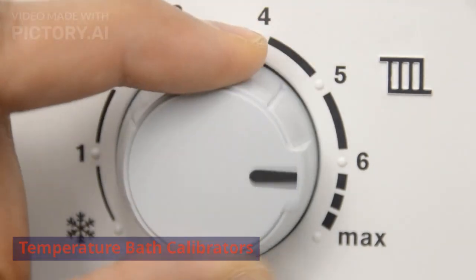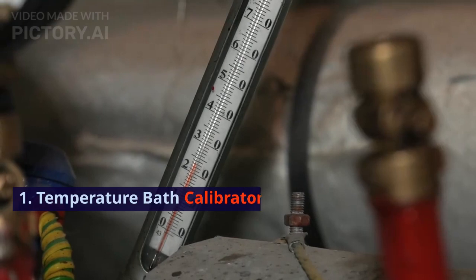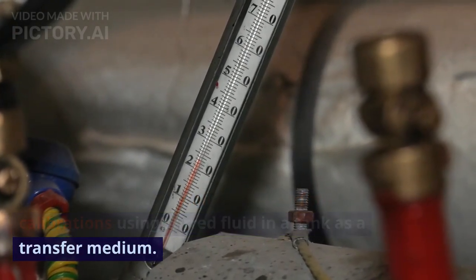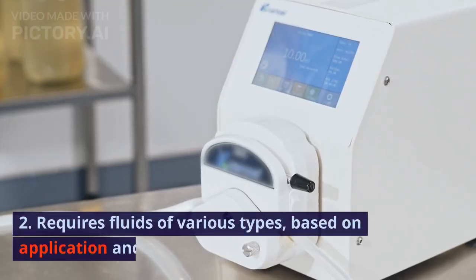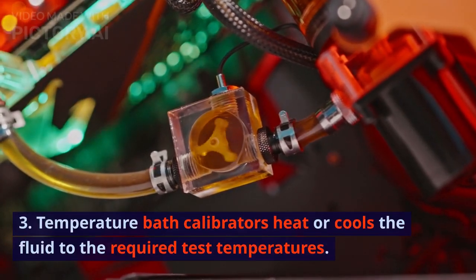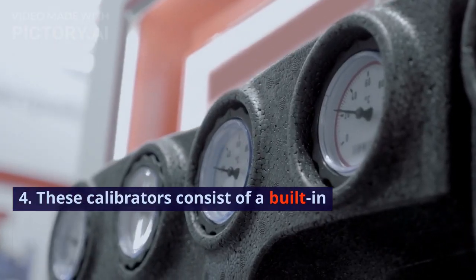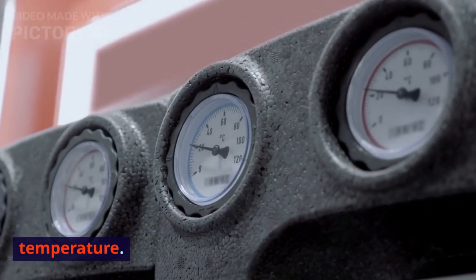Temperature bath calibrators. 1. Temperature bath calibrators perform calibrations using stirred fluid in a tank as a transfer medium. 2. Requires fluids of various types, based on application and calibration. 3. Temperature bath calibrators heat or cool the fluid to the required test temperatures. 4. These calibrators consist of a built-in temperature control system to display bath temperature.